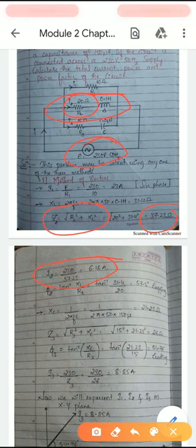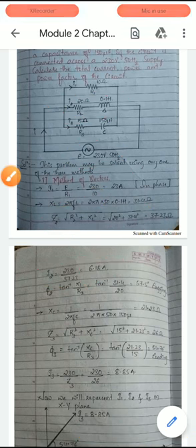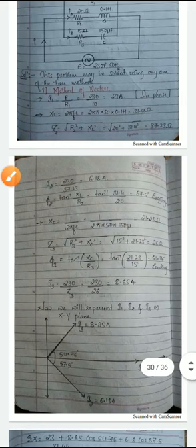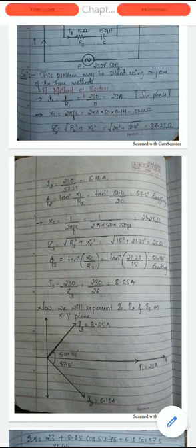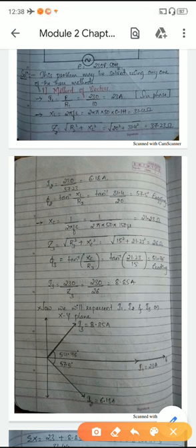Here you can clearly observe that R1 is only 10 ohms, hence the current is more there, but here Z2 is 37.23, hence the current is comparatively less. Next, as it is a circuit consisting of R and L, we need to calculate the magnitude as well as the phase. Therefore phi2 is equal to tan inverse of imaginary part divided by real part.